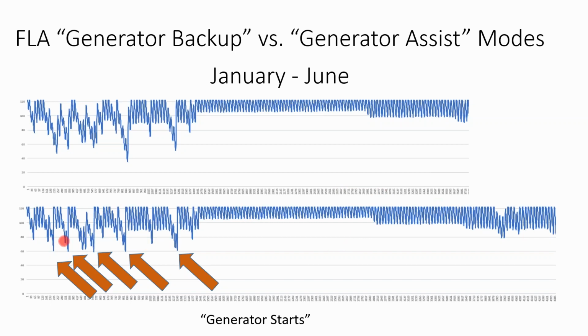But if we're running a maintenance cycle with our generator every 2 weeks while we're deep cycling our batteries, say we're starting our generator in the month of January, we're going to be running our generator five to six times just to protect the battery bank, whereas we might only run the maintenance cycle twice or three times in that month. So as long as we're timing our maintenance cycles with days where a cloud system has passed through over a 5-day long period, we're really not running our generator much more than we would normally be for maintaining the batteries.